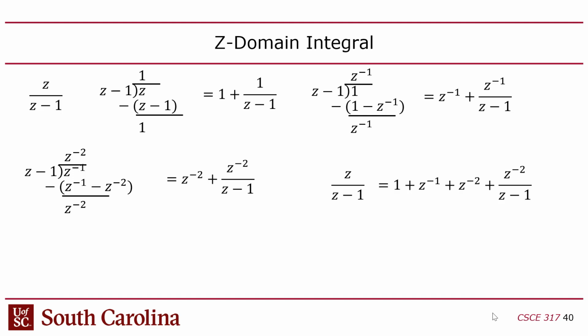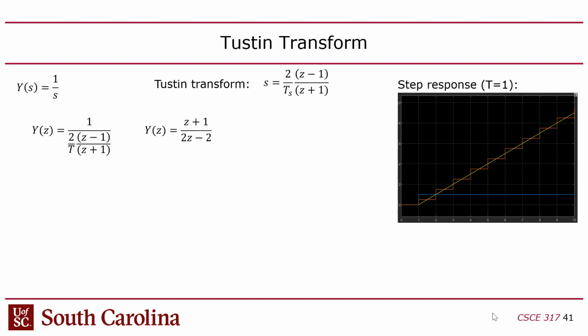If you look at this, all you're doing is a summation, because you're going to take the current sample plus the previous sample plus the 2 samples ago plus 3 samples ago plus 4 samples ago. You're just adding up. You're just doing a summation, right? Again, assuming that you're treating z to the minus n as the sample that you received n clock cycles ago, or n samples ago. So it kind of makes sense why this expression is the integral. Yeah, so that's essentially what you get. It's the same as the integral.